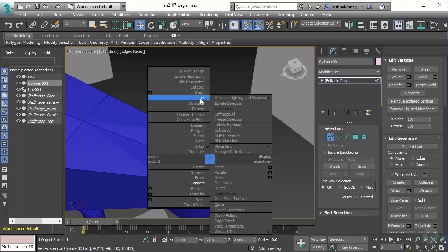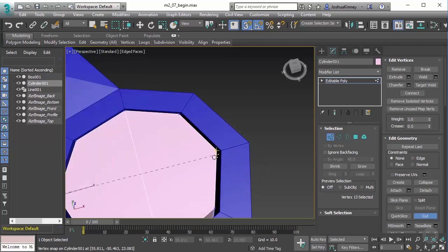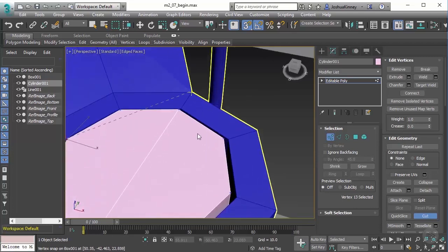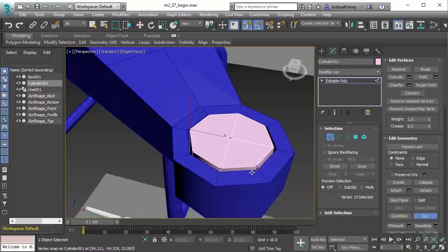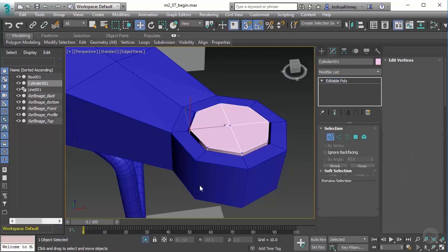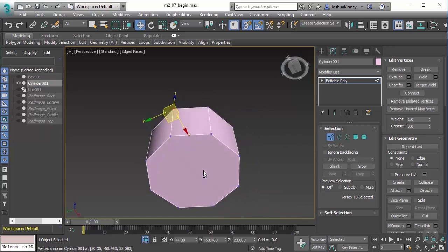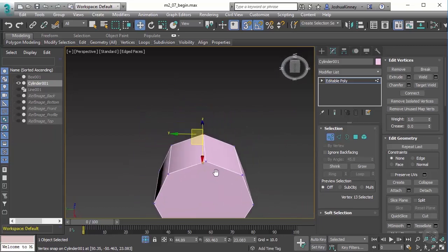Let's go ahead and right click and let's go to Cut, and let's left click on this vertex and go to this one. Now you might have to move the mouse around to get that to associate. If you don't see the icon, it probably will not cut to that. So you just need to move the perspective. Now with this, I'm going to go ahead and isolate it because it's now inside of that other object. And so if I isolate it, it's going to turn everything off but the object that I'm working on. So now I can come in and I can cut on this piece.